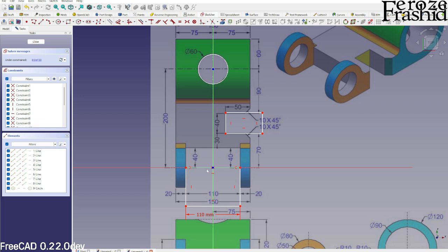So when we apply symmetry, depending on which reference object we are doing it against, it can be fixed or it can be mobile in one direction. We need symmetric by this axis, so it can be moved up and down, and then I can say this distance is 40.